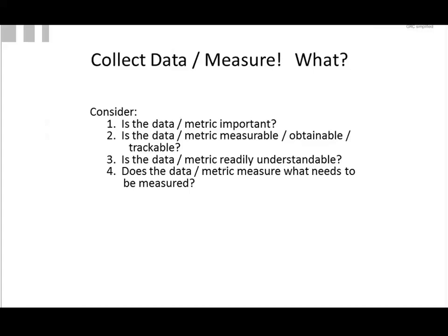What are your key quality attributes? Do you know your sources of variance? Are you able to reduce variance within lots and between lots, homogeneity within lots and between lots, consistency within lots, between lots? So that's a key point, all tied around variation. And you measure that by things like this, or control charting, for example, is an excellent tool to sort special causes from common causes, as the late Dr. Deming would be talking about.